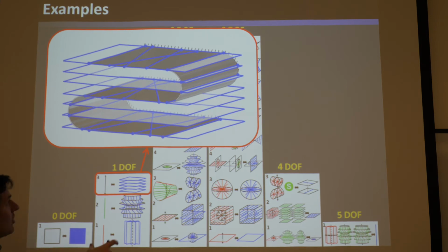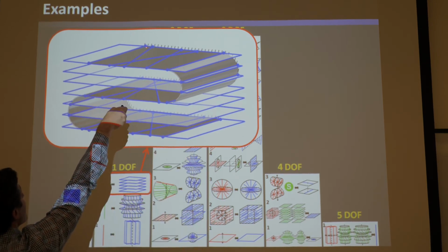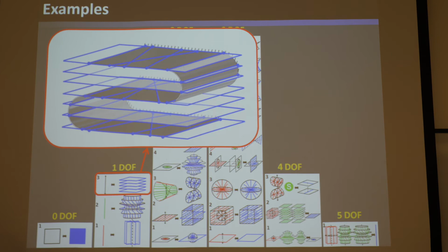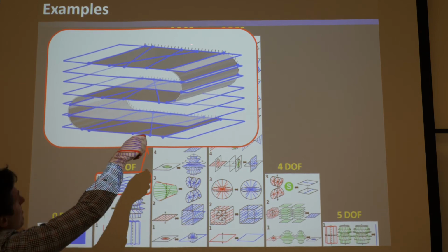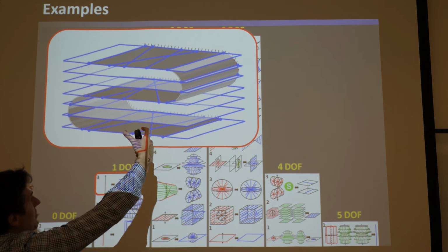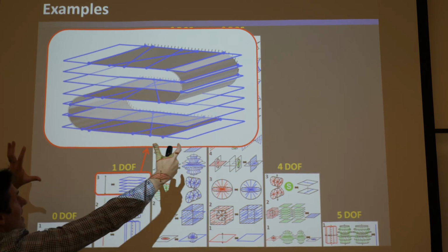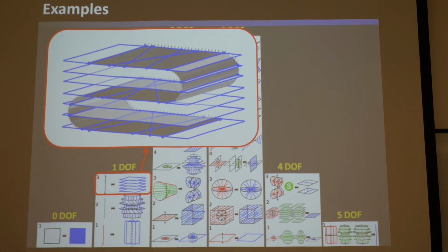Okay, if you connect one of the rigid bodies on this side and the other rigid body on that side, then it definitely doesn't satisfy the condition of a parallel element. It would be a serial element. Okay, it would not work. But if you connect this back side that you can see with the hatching here to a ground or a stage, and then you connect this front side to another stage, so you kind of sandwich it like that, then that is a parallel element.